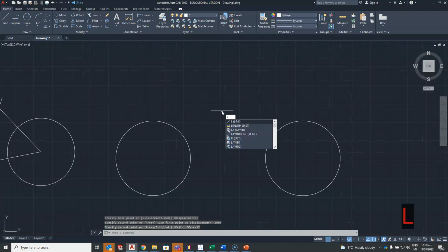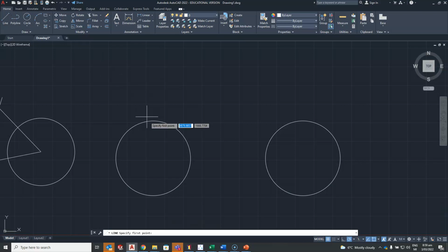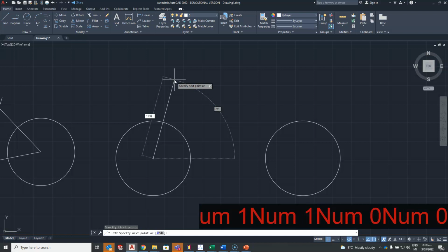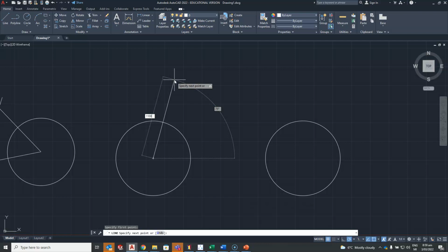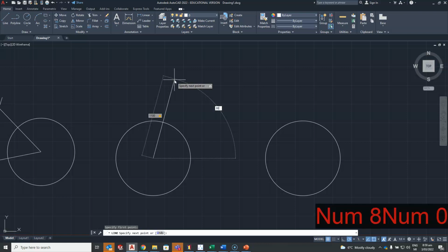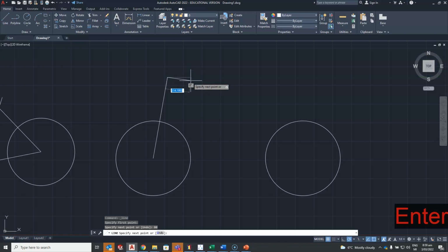If I go and choose line, center. So this time again, I could choose, let's put in 1100. And if I know the angle I want, at the moment you can see off to the right there's a 75 degrees. So it's currently at 75. If I push the tab button, I can now go in and enter a value. Could make it 80. And so I can start to draw things a little bit more accurately.